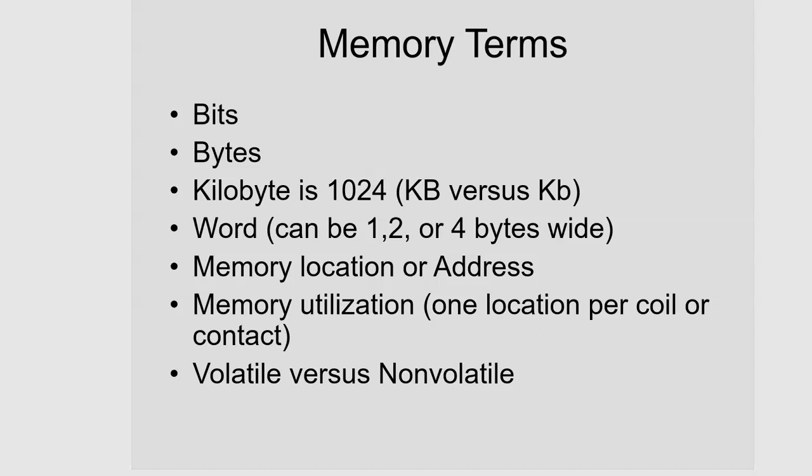Now, what does that mean? Well, being machine dependent means that whoever designs that machine, that computer, that phone, they have control over the word size. They can make a 32-bit word if they want to. And that's important to know because, as someone asked in one of the lectures, the actual word size dictates in a lot of cases some of the physical construction of the machine. For instance, in our class, we're going to use a 16-bit word. Well, what that means is your input module or output module is going to have 16 terminals you can connect to. Your input-output table, image table that we talked about, there's going to be 16 rows there that can store bits, and so that becomes very important.